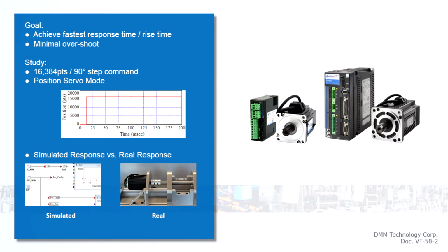In developing the DYN servo control, one of the key performance factors is the servo response time given an instantaneous step command. The overall goal is to achieve the fastest rise time with no overshoot. The step response is an important specification for the servo as it tests the dynamic relationship between acceleration and torque.